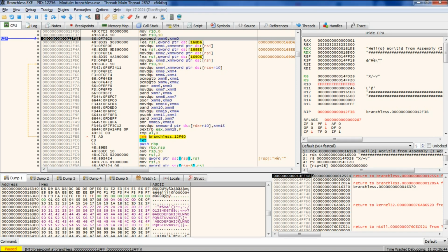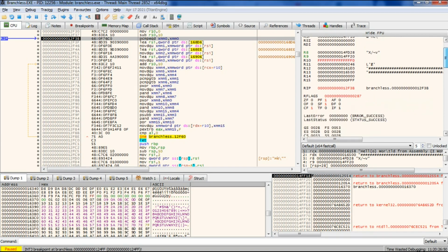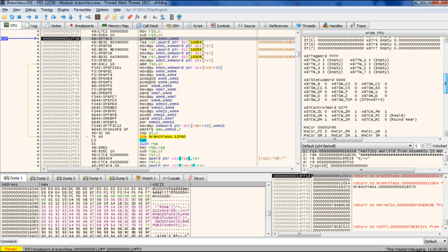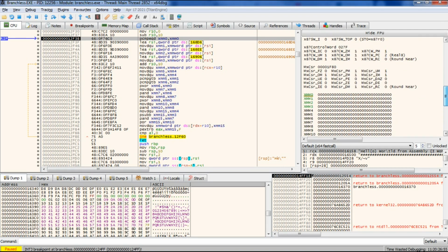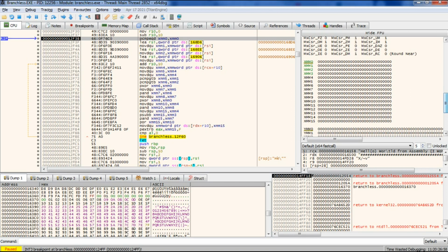Okay, so I've already executed a few steps here. Here's our register window. I'm going to drag this down. There's a lot more registers available than what we've been using. Here's a set of registers that also exists. These are 16-byte registers. Below them are more registers, but we won't be using those today. First, we've already got R10 set up, subtracted 10 from it. We're still outside of our do loop. We're going to do a little initialization here and load in a few buffers.